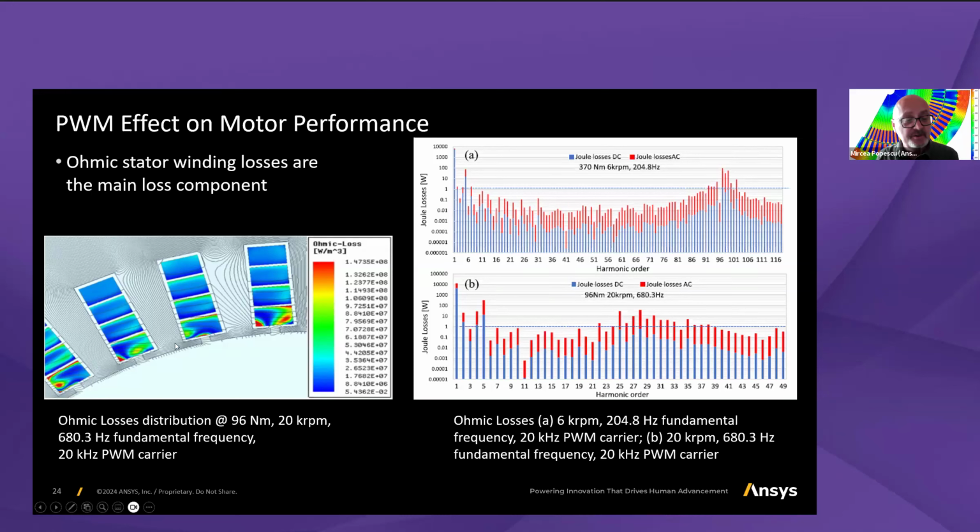And you can see the ohmic losses, how they develop. This map is including both the DC and AC loss components inside the winding. And you notice the lower conductor, the conductor placed over the slot opening, they all are suffering from a higher thermal stress point of view, because the losses will be higher.